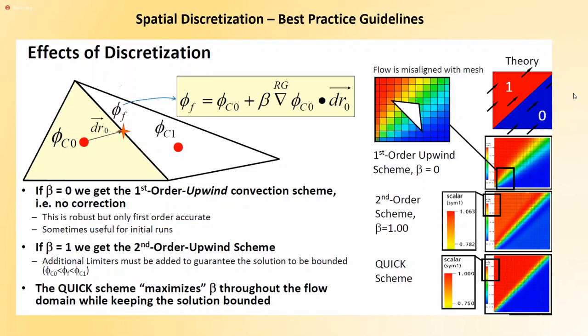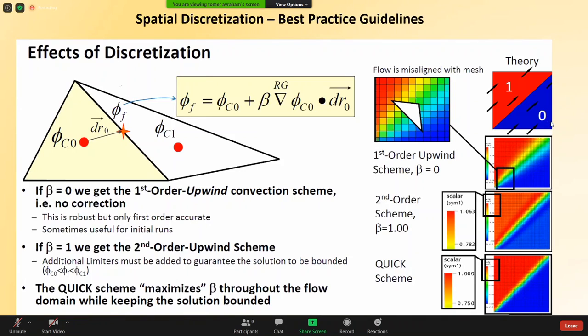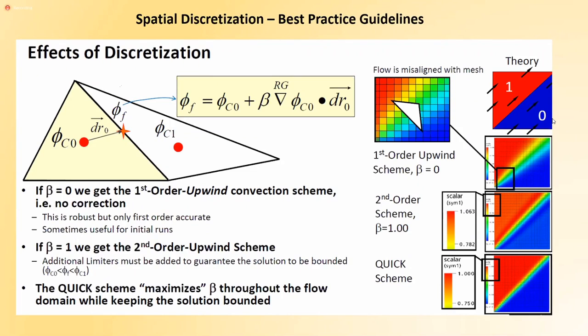What's good about it is that it allows us to get closer to the solution. First order upwind will not be tolerated in any publication. You cannot even offer a publication when you did a CFD with the first order scheme.